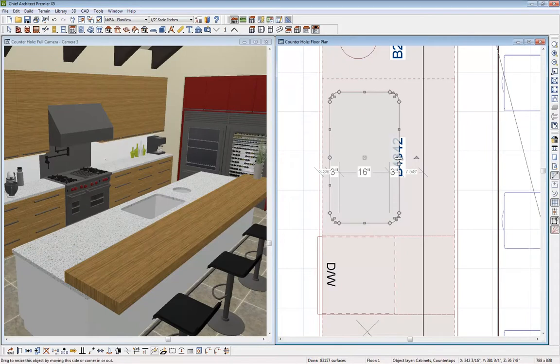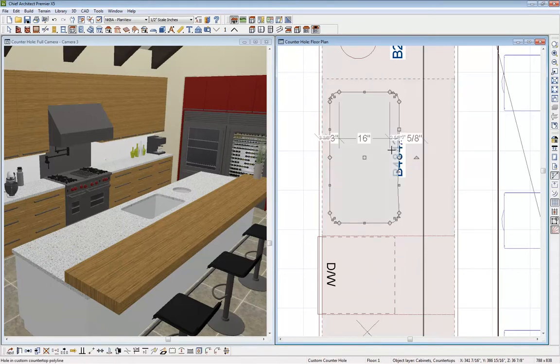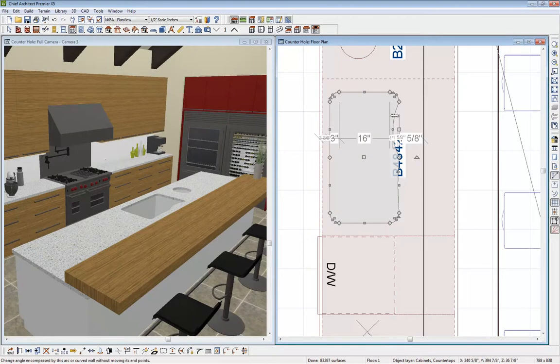And now let's make a curve on that. So I'll be using my change line arc tool down at the bottom. So with one click it will change that, and then we can change that radius. Let's just bring it down a little bit and work our way around. So again, if you don't select the right object, just hit tab, and that's a very quick, easy way for you to select that edge again.